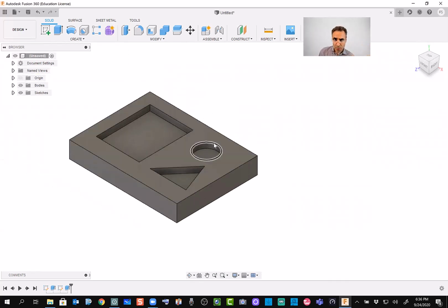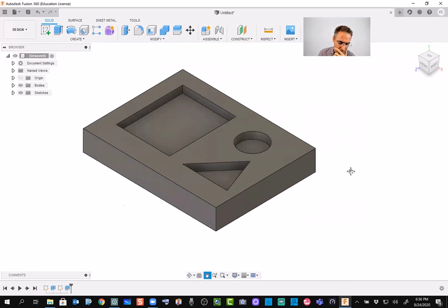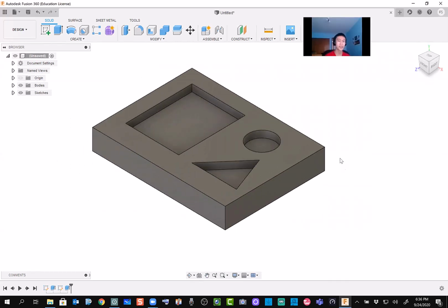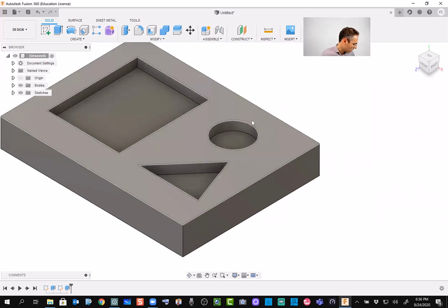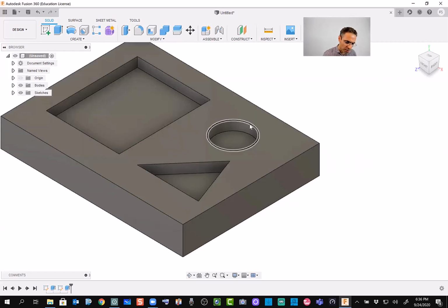Now it's time to do milling for this one, but do you guys think that we can machine this one down and create these pockets? Is it okay to do that? You need fillets. Great, yeah. These sharp corners, we cannot really machine and create those. Our tool is going to say, sorry, I cannot do anything for you. So, as Jesse pointed out, we need fillets.